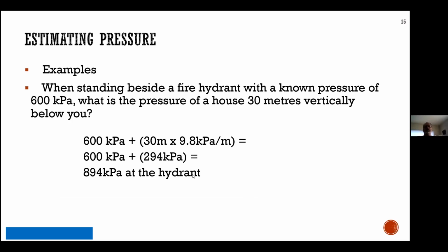And there will be math questions like that, where you will be given an elevation, and they'll ask what the elevation is, or the kPa, at this different point. At that point, you really only have to add or subtract. But if you draw a picture and realize that the top water level of the reservoir is here, if I go lower in elevation or add another lower in topography, then I know I'm adding that together. If, in fact, I'm going to higher ground, I'm actually subtracting it because the pressure gauge will have less of a column above it. So drawing the picture really helps.